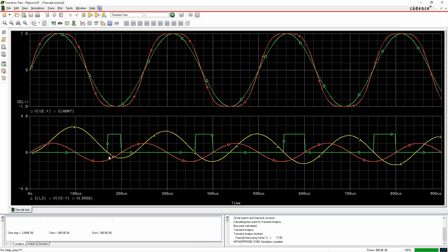The green color pulse shape waveform represents the output of a MATLAB custom function block. As you can see, that it accurately detects the third quadrant mode of operation from my voltage and current waveform. One can use this output in power controllers for further processing.